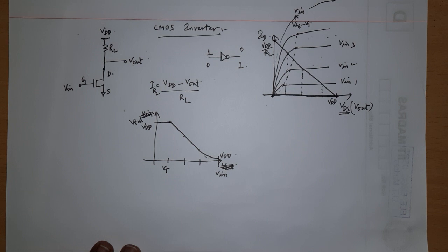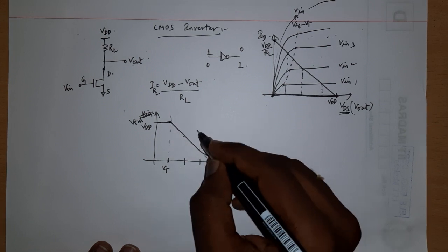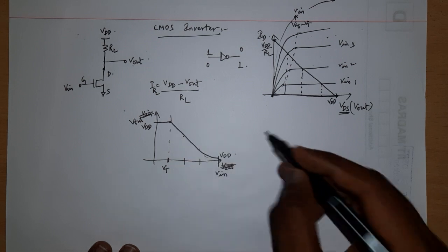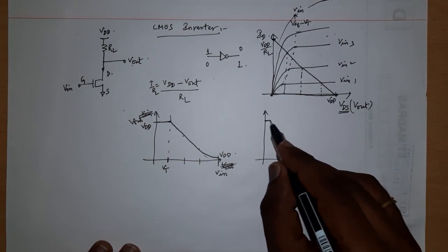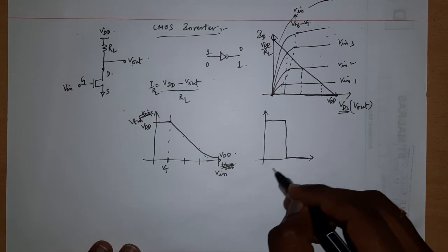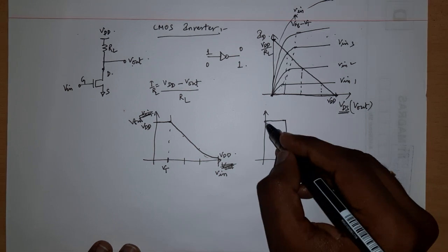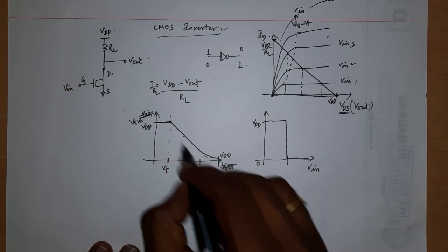The problem is that it has something called a noise margin that we will declare later. Like, sufficient amount of margin should be there. Okay, so what I mean by that is, I want an ideal inverter to behave something like this. I give some kind of V in which is lower than some marginal value. It will always give VDD, and beyond that it will always give 0. Okay, but it is not so.